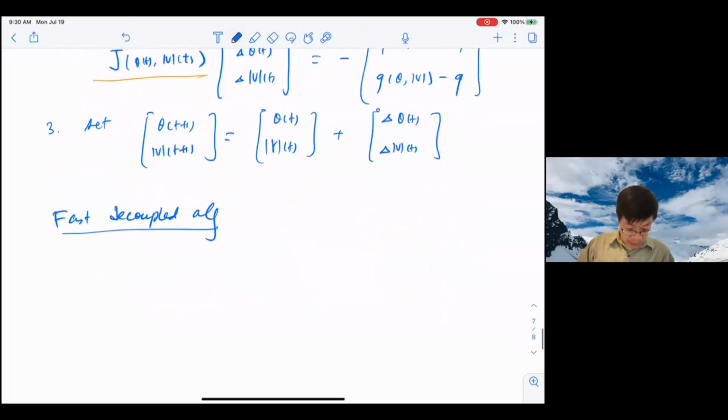If we take a closer look at the Jacobian, J_K, well, there are two parts, there's dP and there's dQ. So just to simplify notation, let me go directly. The P_j here is the function, not just the given scalar, but the function of theta and V.